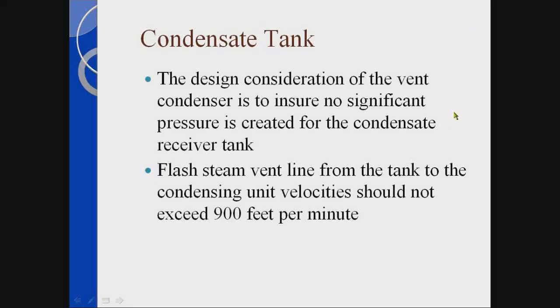Oh, yeah. Great question. See, I didn't even understand the question. Yeah, I understand his question. It's a great point. Thank you for bringing that up. The only place that we say it's acceptable for steam to be vented to the atmosphere is off the deaerator. If you don't know the volume, you have to vent 1/10 of 1% of the volume of the deaerator to atmosphere to make sure you're getting rid of non-condensable gases out of the deaeration process.